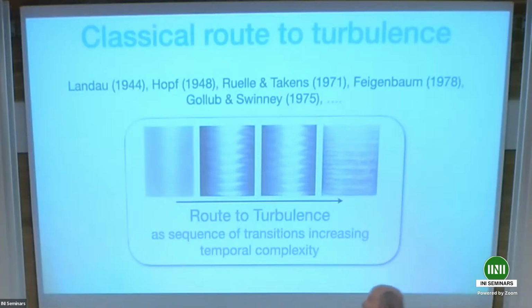And I think that the pinnacle of this was this work by Swinney and Golub. Again, this is Taylor-Couette, but now I'm only turning the inner cylinder. They are only turning the inner cylinder. So it's not the counter-rotating case, it's just rotating the inner cylinder. And what happens is you go through a sequence of instabilities. The first instability gives you the Taylor vortices, which I think is generally familiar.